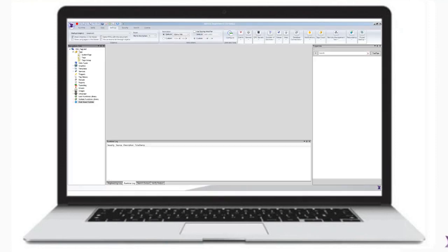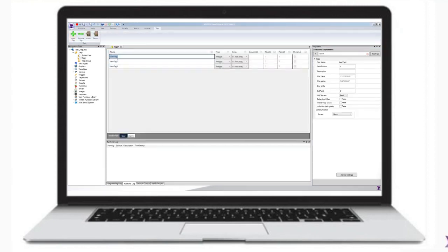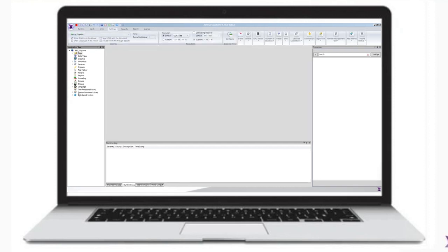The rule-based system can also be used to control simple tasks. Let's create two rules to control valve flow. It might be an alternative to the text box limits, which you will still see in this video, but using rules instead. To begin with, let's create 3 tags. The valve tag and the others representing the low limit and the high limit of the valve.